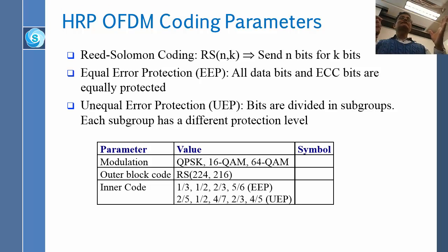Okay, so this is all selection, how you select the polynomials. All of this is actually done in polynomials. But anyway, so this is that. And then after everything is done, we do the modulation, which is when we send on the air, we can use QPSK, 16 QAM, 64 QAM. Right? So there are 3 codes. If you want to call them codes, this is modulation, and these 2 are the codes.